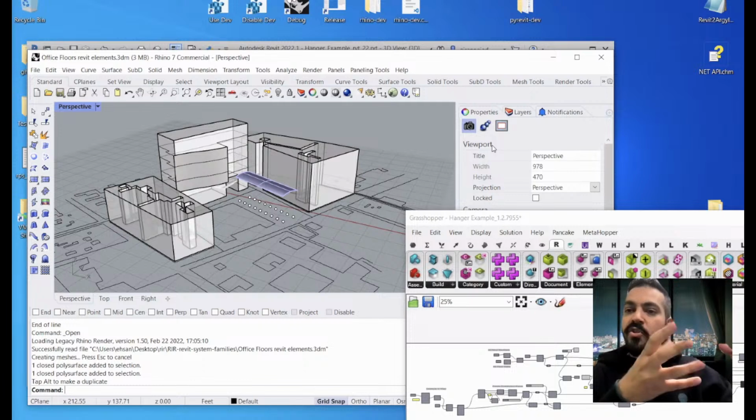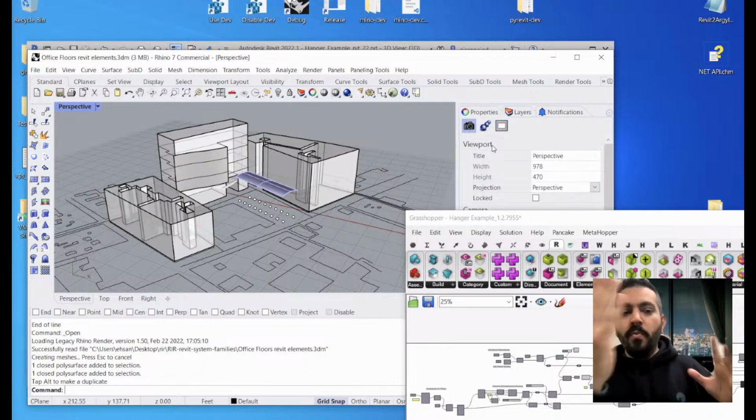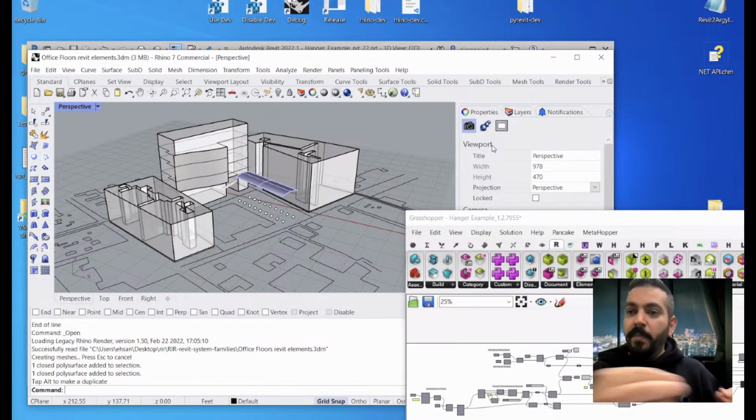Sometimes you have a geometry on the Rhino side because it's a little bit of a looser application, right? It's not BIM. And you may want to extract, like if I have a wall, I may want to extract the base curve, and then use that to actually create a proper native Revit wall in my model. So Grasshopper gives you full control over this translation process.